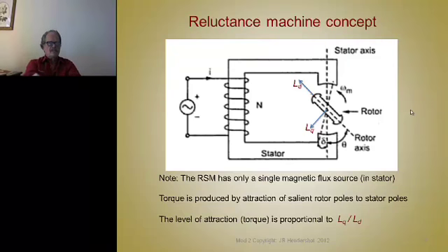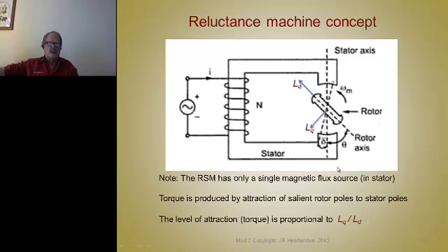Now, a reluctance machine works differently than the brushless or the induction, because it has saliency. What does saliency mean? Let's talk about that for a minute. We're back to our transformer core here with a coil wrapped around part of it. In this core we cut a section out, and we mount that piece on bearings with a shaft, so it's allowed to rotate like that.